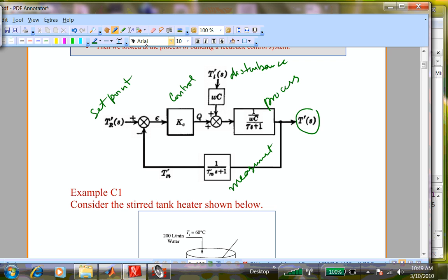All these features are built into the control station software that you have, but for a few specific processes, like a two-tank drainage or a heat exchanger or a distillation column. What you are learning is to be able to plug any process model in this place. Instead of that block, if you have a model for a fluidized bed reactor that you want to control, you just have to know the transfer function for that and put it in there, and you have a control system. And there are several parts to it. One is controlling it for disturbance rejection.